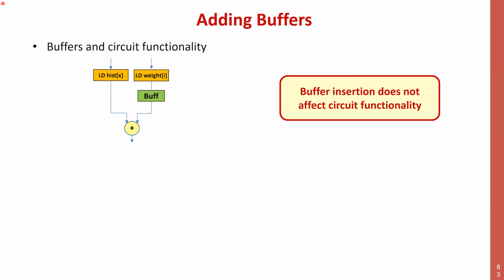Right? If I put a register here, I delay this value, and the operands that I'm ending up summing up are not the same as before, because one of the two streams of operands is delayed by one cycle, so everything is wrong, let's say.